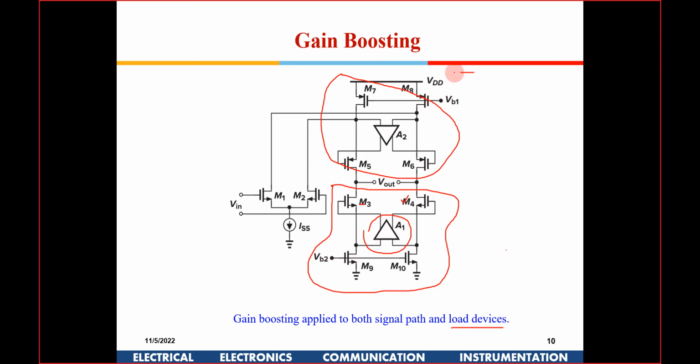So finally, if you want to make a circuit with very high gain, this is the kind of circuit you should look forward to. Okay, so this is a cascode structure. It is good for high frequencies, right? And this is very high gain, you can get a gain of 200, 300 of that order instead of 10, 20 which you were getting initially in a simple structure. Okay, so that kind of gain can be achieved with these kind of circuits.